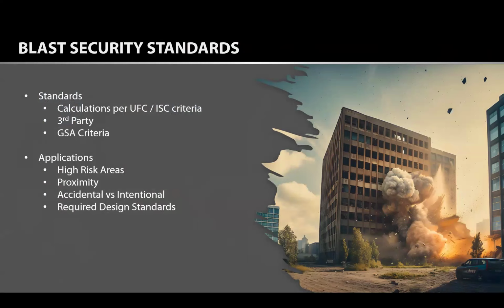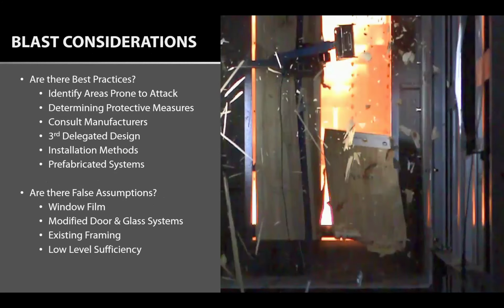There are many different calculations and many different requirements when it comes to blast rated standards. But there are two things that are required on every single project and in every single set of specifications when you are working on a blast rated project. The first actually is the fact that it is required, the standoff distance. The standoff distance is essentially what that distance is from the surface of those buildings from the initial explosion, right? That very well could be 2 feet up to 200 yards away or miles away.